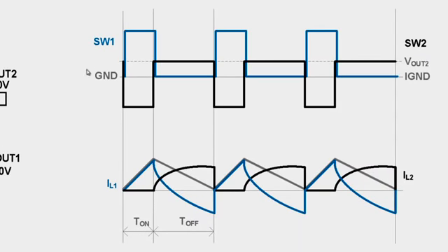On the left side vertical axis we have the quantities for the primary side of the converter, switch node 1 and inductor current L1. On the right hand side axis we have the secondary side quantities, switch node 2, Vout2, isolated ground, and the current in the secondary winding. Also shown is the magnetizing current in gray. The operation of a flybuck converter can be divided in two subintervals in every switching cycle.